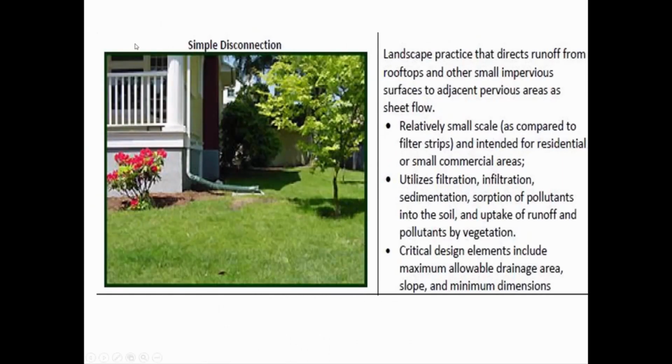All right, here's another illustration, and this is something that's been pretty hot in Huntington for the last 5 or 6 years, is trying to get people to disconnect their roof drains. And I previously already told you about our combined sewers here in Huntington and how about half of the network has both wastewater and stormwater running through the pipes. And when it rains, that stormwater makes its way into the streams and pushes the wastewater along with it. And so if you disconnect the roof drains, then you're going to be reducing the amount of water that gets into the combined sewer.